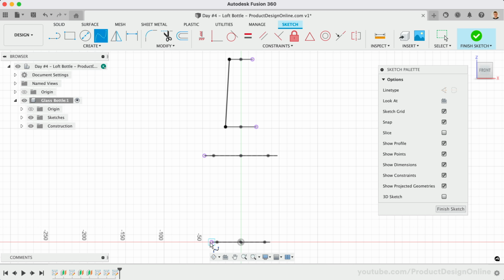Start from the bottom point and select the next 2 points. Remember to press the Enter key to commit the spline, or you can select the green check mark. Really important, we must take the top spline handle and click and drag it until it snaps to our straight line. This will ensure our guide rail is continuous and treated as one line.